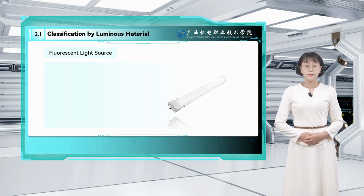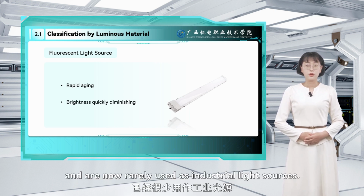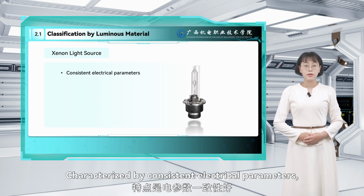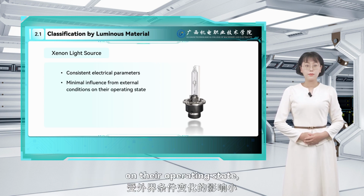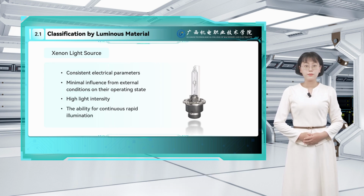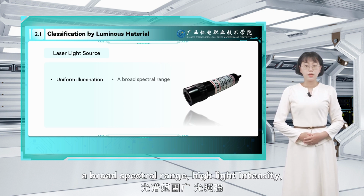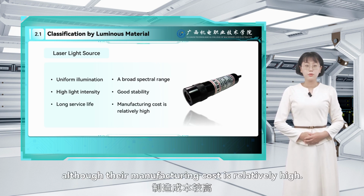Fluorescent light sources. Characterized by rapid aging, with brightness quickly diminishing over time, and are now rarely used as industrial light sources. Xenon light sources. Characterized by consistent electrical parameters, minimal influence from external conditions on their operating state, high light intensity, and the ability for continuous rapid illumination. Laser light sources. Characterized by uniform illumination, a broad spectral range, high light intensity, good stability, and long service life, although their manufacturing cost is relatively high.